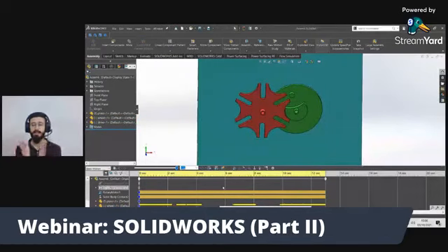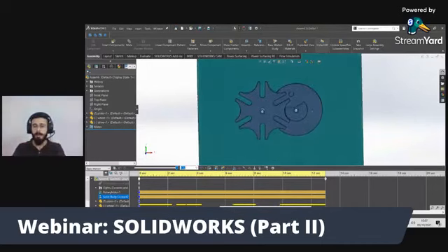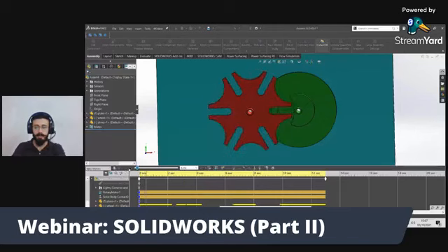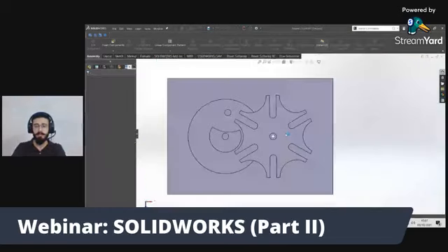Why is this showing this kind of motion? Because of this solid body contact. When you use this feature, SolidWorks automatically identifies the solid bodies. Let me reduce its speed to 0.25, and now I will explain. See, it goes in here. Why doesn't it mix up? I will open the other assembly also, so you can see the difference, what solid contact does.